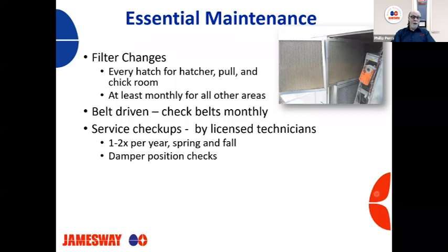We recommend service checkups by licensed technicians, usually 2 times per year, spring and fall, when we're changing seasons, when we're going into our heating season or going into our cooling season. It's good to have these checked then, and also check our damper positions on our RTU units. Make sure that they're operating, the linkage is working, and they haven't gotten out of calibration.